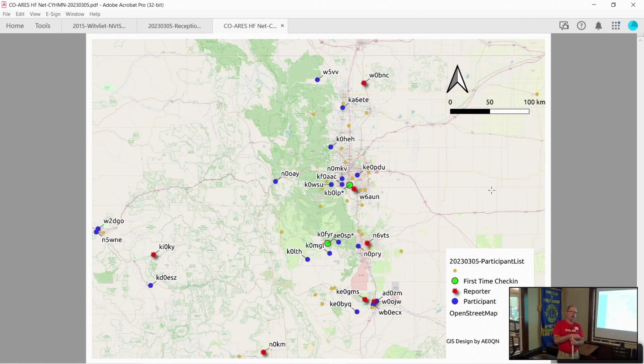Inverted V's are good. A classic inverted V, the legs come down at like a 90-degree included angle, or shallower. You don't want to be steeper than that. If you're going to do NVIS, spread them out more towards horizontal.